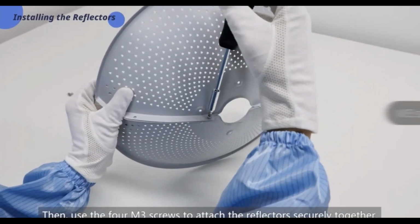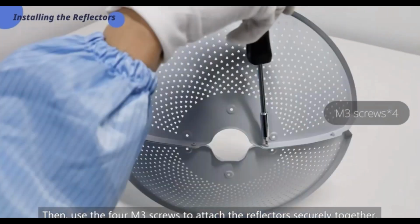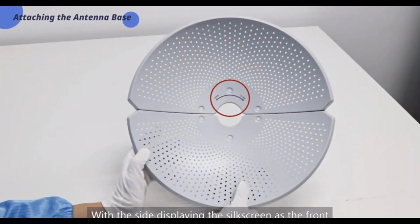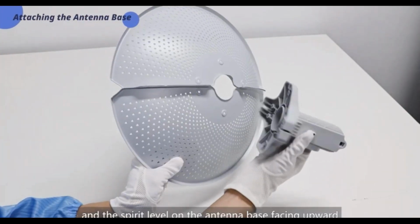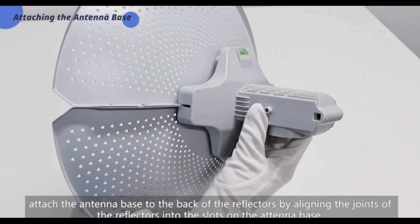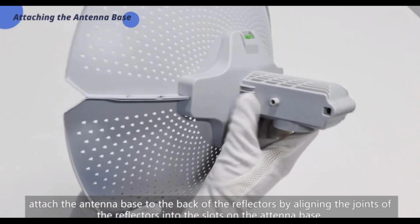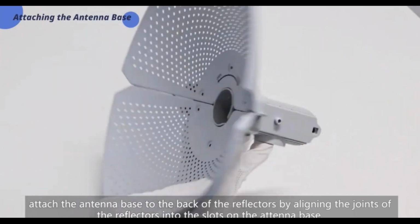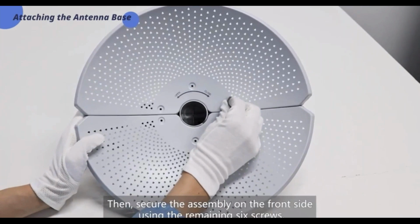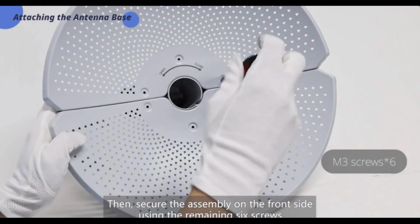Then, use the 4 M3 screws to attach the reflectors securely together. With the side displaying the silkscreen as the front, and the spirit level on the antenna base facing upward, attach the antenna base to the back of the reflectors by aligning the joints of the reflectors into the slots on the antenna base. Then, secure the assembly on the front side using the remaining 6 screws.